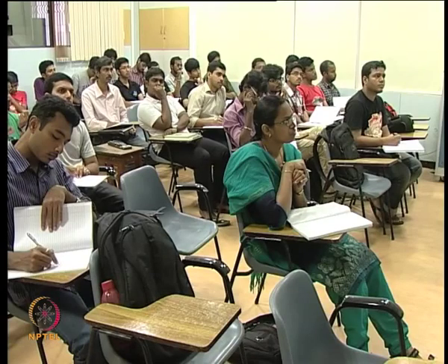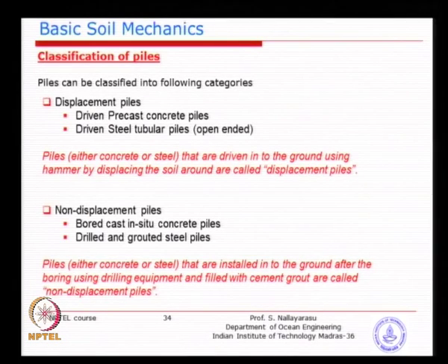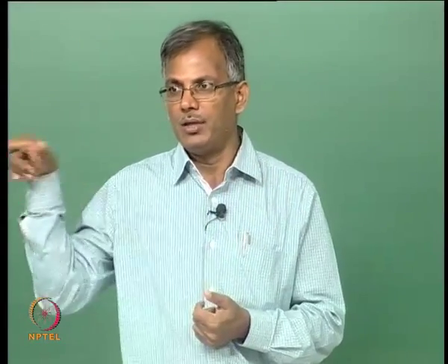I think that gives you an idea between a displacement pile and a non displacement pile. How and why we need to know this is to get an understanding of the soil behavior. Here you are disturbing the soil, whereas the other one is your better densification, especially in the coarse grained soils.